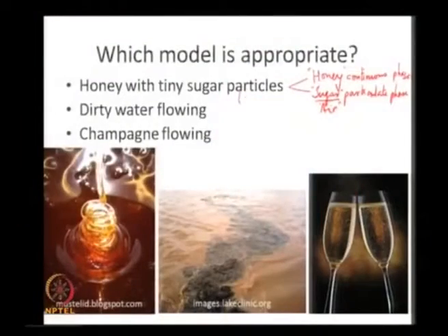I think we can see that it is generally going to have to be true. That is, the bubbles cannot be moving with a vastly different velocity than the honey locally. Okay. So, this would be a good case for the mixture model, and we will see quantitatively how to find this.